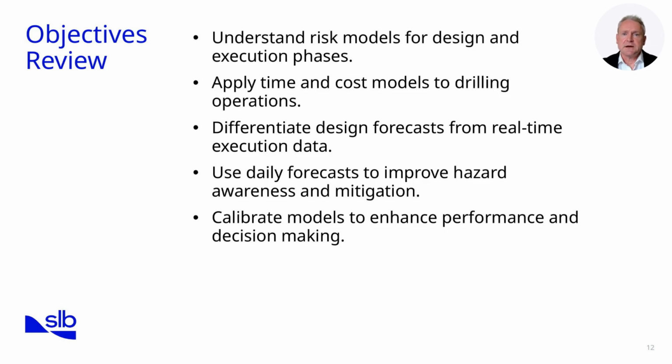Second, we set out to apply time and cost models to drilling operations. We reviewed how these models justify project economics in the design phase and support real-time performance decisions during execution. Third, we focused on differentiating design forecasts from execution data. We highlighted the importance of calibration to bridge the gap between assumptions and reality. Fourth, we explored daily forecasts as tools for hazard awareness and mitigation, strengthening both proactive and reactive responses from the drilling team. Finally, we emphasized calibration as the key to enhancing both performance and decision-making.